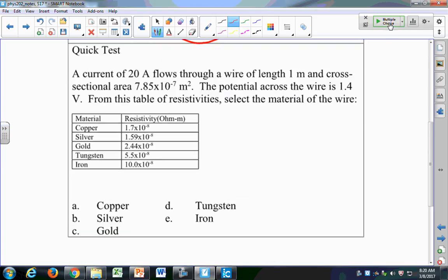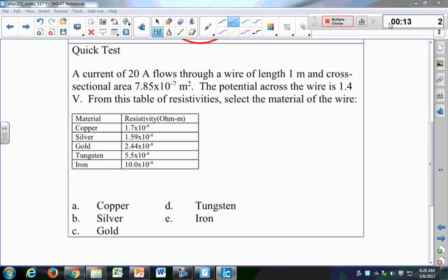All right, this is also a nice question. You'll probably see a question on your test like this, where you have a metal and you just don't know what the metal is. A simple way to determine it: you can look at its color and its density and all that stuff. You can also apply a voltage to it and measure the current, and then calculate the resistivity. So here, what you want to do is first calculate the resistance by Ohm's law, and then calculate the resistivity based on the dimensions of your wire. You did this in lab, but it's a nice way to determine unknown metals. Let's try it out. You have a homework question like this. You'll probably see it on the test too.